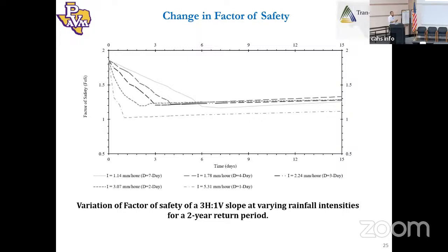Now, your friend is trying to save the slope, and your enemy is trying to fail the slope. So friend over enemy means friend is the shear strength of the soil, and the enemy is the applied stress or the reduction in the strength. Because of the reduction in the slope soil strength, your enemy is increasing. So factor of safety 1 means your slope is at the verge of failing, right? If your slope factor of safety is less than 1, that means your slope has already failed. And if it is more than 1, that means your slope is stable.